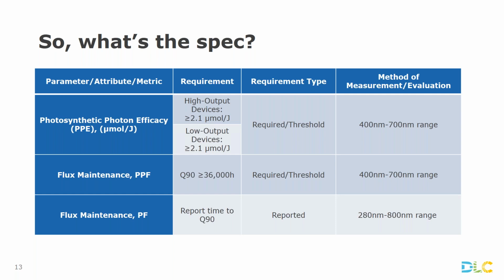And I suppose that if there are things that are even outside of that, then that will be reflected in the energy budget. That 2.1 micromoles per joule is total joules input to the device, making all kinds of wavelengths, but we're only counting the output wavelengths of PAR. And so if tomorrow it was to be found that a certain wavelength outside of the ASABE range was critically important, but was not uniformly testable, one outcome might be that that energy budget might come down so as to allow for more photons to be emitted in that wider area that we cannot reliably measure at this point in the fixtures.